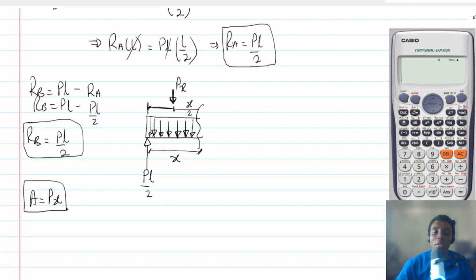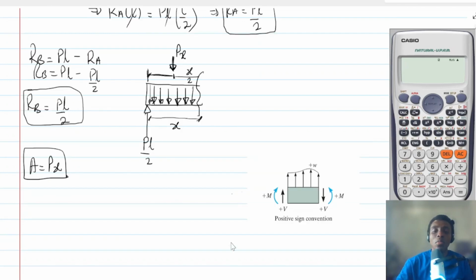Now you've seen something like this here. What this means is that there will be a shear force coming down here. Let's call it V, and then there will be a moment coming this way. Let's call it MX. Basically, we are doing this because we have taken a section, so that is why the moment and the shear force are coming there. We call them internal forces. All right. So now that we have been able to do this, let me try and magnify this small.